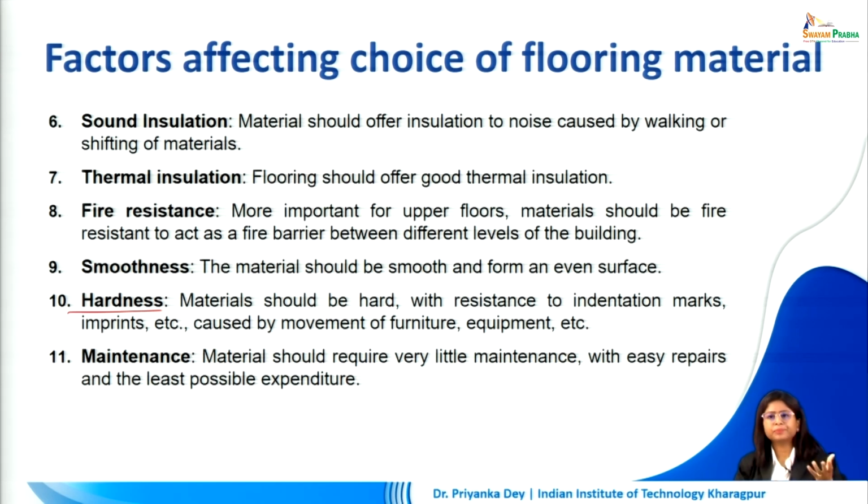Let's say we have indoor stadiums where games are played. It's possible that that vibration would get transmitted into the galleries in which the spectators are sitting. So we want to isolate the flooring from the overall structural members with the help of some gap, and the material should be such that it doesn't transmit those vibrations very easily. Also, it should be hard enough to constantly go through these changes and impacts over the use of the building.